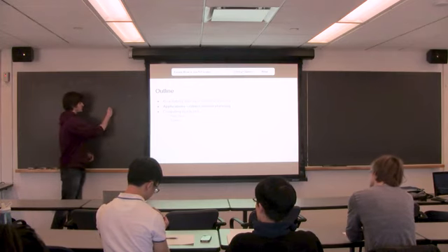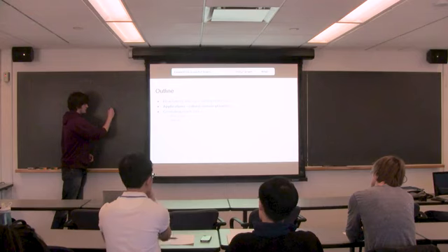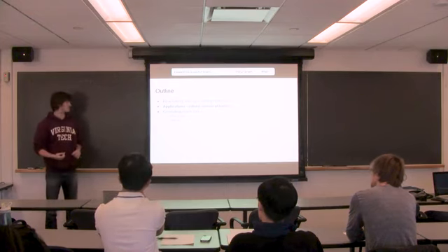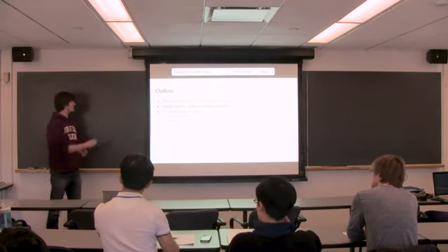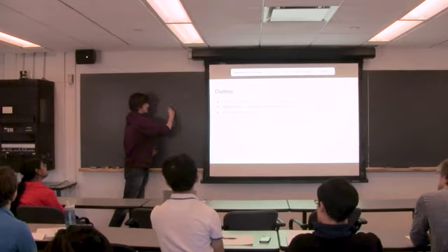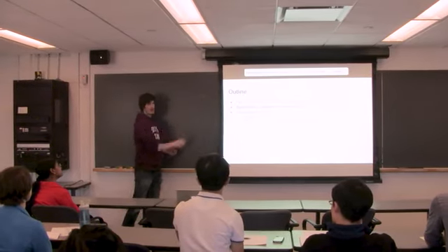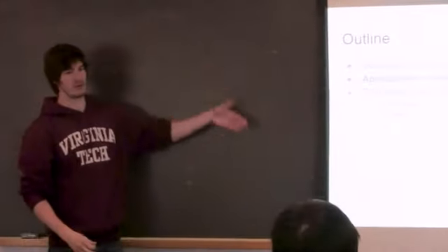If you only compute two funnels, one of them goes over here and one of them goes like here, then you're not going to be covering the state space. So it depends on how much computation you want to do offline previously. You compute a set of funnels that's here, another one that's right here, another one that's here, and you have your big library of funnels that cover the whole space.